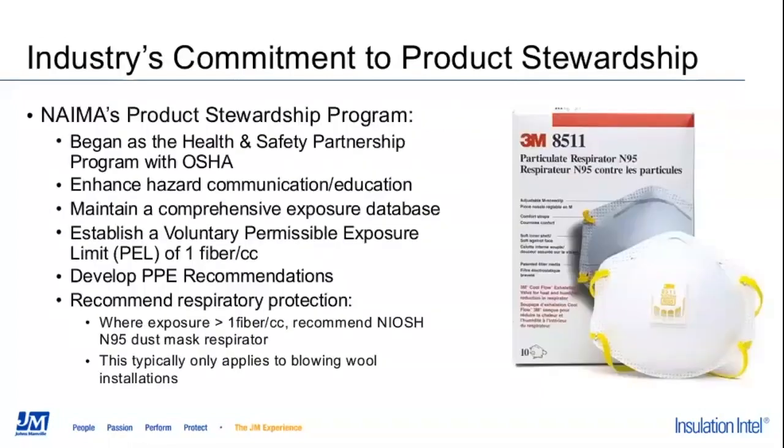So that side of product stewardship isn't just unique to Johns Manville. It's actually an industry commitment to product stewardship. So our Product Stewardship Program began as part of the Health and Safety Partnership Program with OSHA. And this program was designed to enhance hazard communication and education, just like this webinar today, maintain that comprehensive exposure database that I already discussed, establish the voluntary permissible exposure limit of 1 fiber per cubic centimeter, and then develop personal protective equipment recommendations around any of the findings that we revealed from this research.